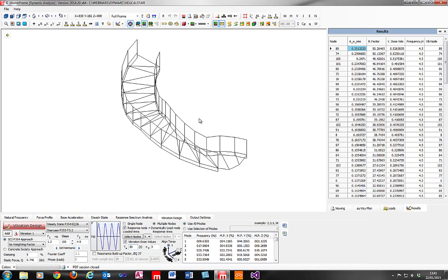So you might estimate that somebody could walk down the stairs in 30 seconds. So that's the duration of the loading. The NA is the number of times this excitation may occur over a design period. Typically the code splits it up into days and nights. It talks about an 8-hour night and a 16-hour day. So I might say there's a possibility at a maximum that this stair would be used 10 times over a 16-hour day.